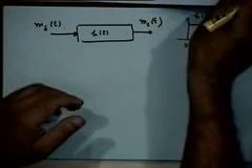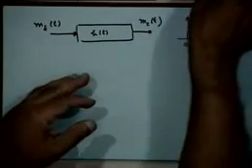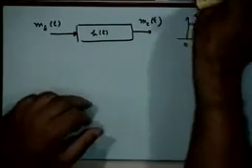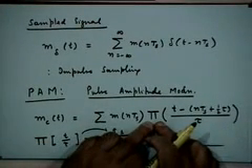So, I am sure when you did your sampling theorem, you talked about impulse sampling, natural sampling and flat top sampling. What kind of sampling is PAM? Flat top sampling, right. PAM is essentially kind of flat top sampling, as you can see. That is what the definition is. You are having a flat top pulse.